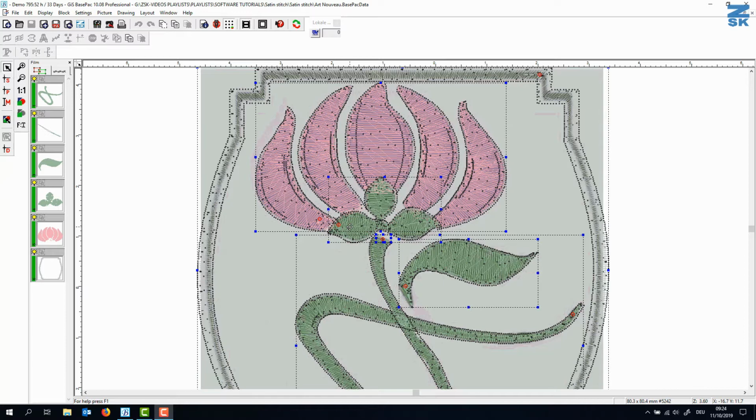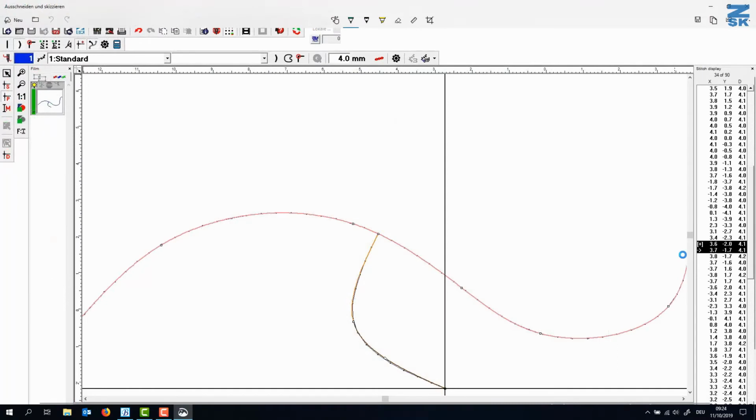This percentage pull compensation is actually only regarding the satin stitch or the tatami stitch. But you also might come across this expression in the running stitch. Where do we need it in the running stitch? You see here we have a running line with a subline. Now if I program this, I think it looks all neat. Then you run it on the machine and actually this point here will not be perfect at the edge.